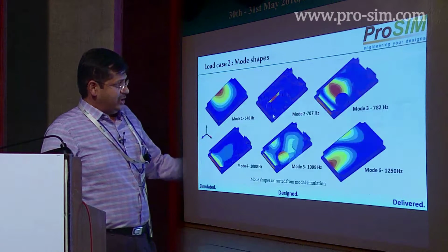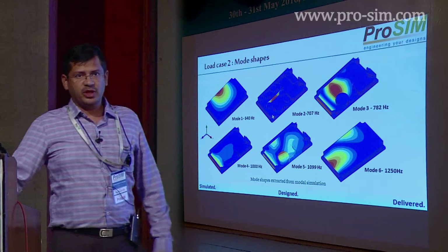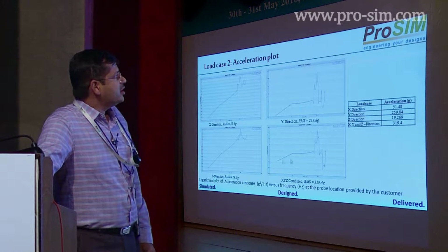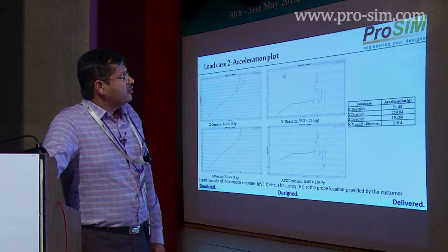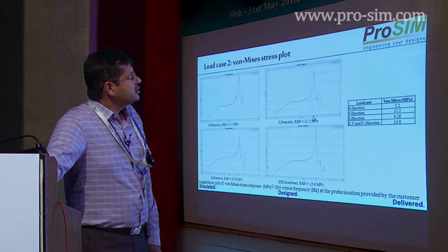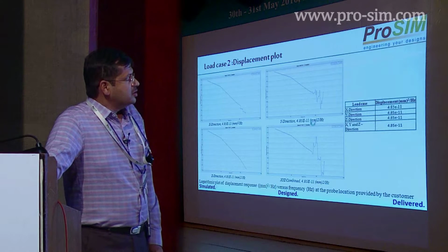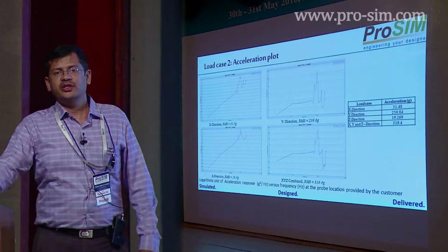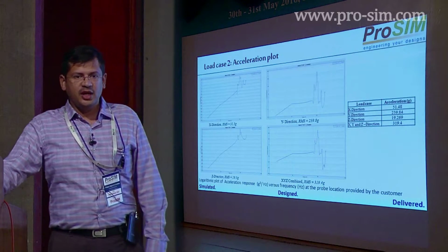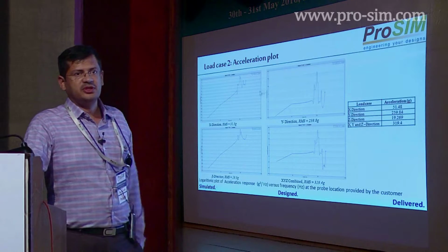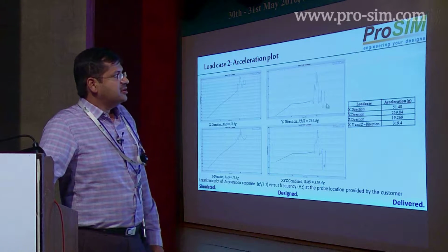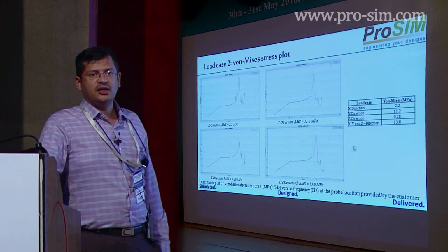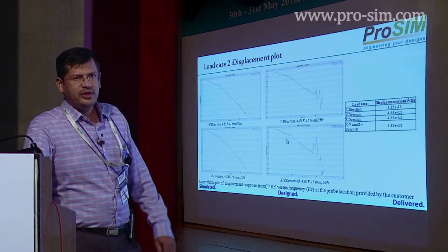So this, as I told, there were 3 probe locations, out of which we plotted close to XYZ direction, and also combined XYZ for acceleration, Von Mises, and displacement plots. In all these 3 probe locations, we found that the second probe location was the peak location, and even that peak location I have just represented here as a snapshot, and this acceleration was plotted. Von Mises stress also was well within the allowable limit, close to 120 MPa, I remember.